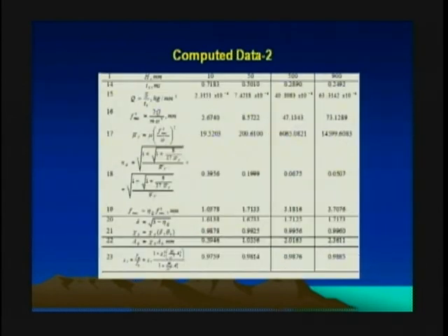And here are calculations of other parameters depending on the drop height. As you see, the drop height, which characterizes the degree of nonlinearity, changes by a dramatic factor of almost 190. And the accelerations, yes, and displacements, they change significantly, but not that dramatically.